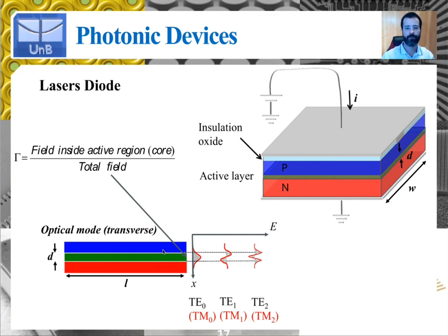In optical waveguides and in optical fibers as well, the core of the waveguide, the region with the higher refractive index, let's call it NC, and on either side you might have an N2 referring to the index of the cladding regions, in such a way that NC is greater than N2. But for such a waveguide, the transverse mode will have a fraction of it which is not inside the core. This is called the evanescent field.